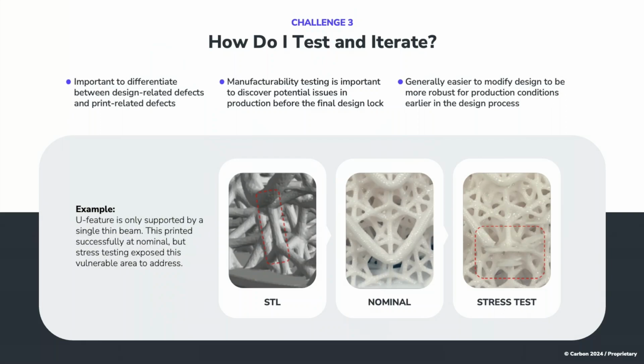And the reason that we do this is we want to test to discover the difference between a print-related failure and a design-related failure. Because print-related failures, one-off problems, they're really easy to solve for. You just turn the printer off, turn it back on, the problem takes care of itself. Design-related defects, as it turns out, they're a little harder because this little piece might work 8 out of 10 times, but on printer number 10, that a certain operator doesn't necessarily clean fully, maybe the resin, there's a little bit of lot-to-lot variation, it'll fail consistently. So you're going to throw a lot of flags. It becomes a real challenge.